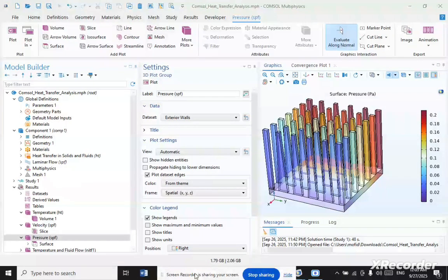The micropin fin arrangement of the microchannel heatsink has been thoroughly researched in the current review. Compared to microchannel heatsinks, which favor improved thermal performance, micropin fin heatsinks have several intrinsic benefits like higher convective area, secondary fluid flow, vortex production, and thinner boundary layer. Different design approaches have been made in micropin fin heatsinks to enhance heat transfer due to the fast rise in heat flux in various electronics. The design alteration in the micropin fin heatsink can positively or negatively influence flow characteristics.